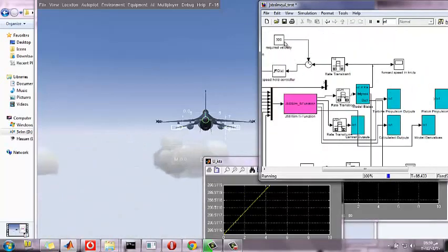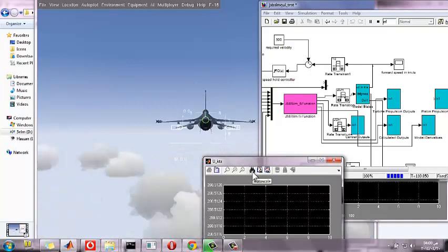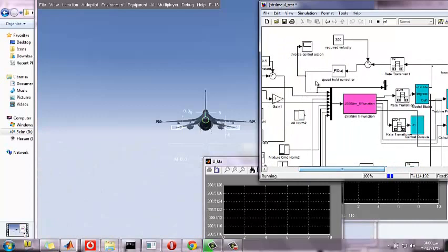You remember that we ordered this controller that we wanted the aircraft speed to be about 300 knots, and here we got about 289 knots, which means that we have about 10 or 11 knots steady state error, which is acceptable regarding that this controller that you see in front of you is just a controller that is made by sense, not based on any numbers or calculations, just for playing around, no more no less.